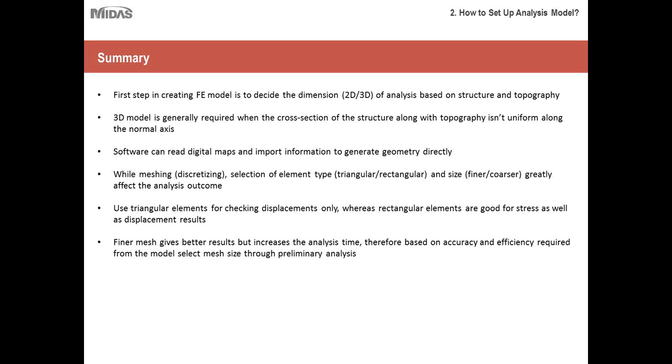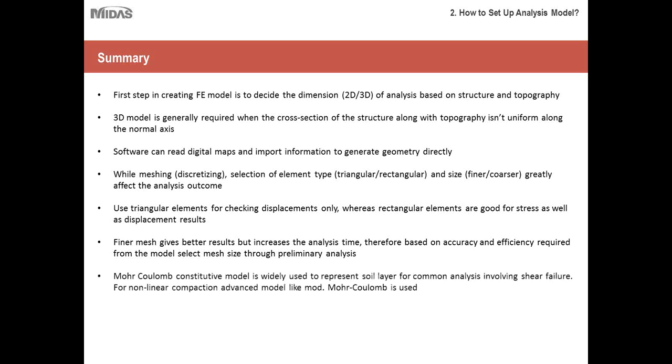Finer mesh gives better result but increases the analysis time. So therefore, based on the accuracy and efficiency that is required from your model, select the mesh size through preliminary analysis. I hope this point is clear.